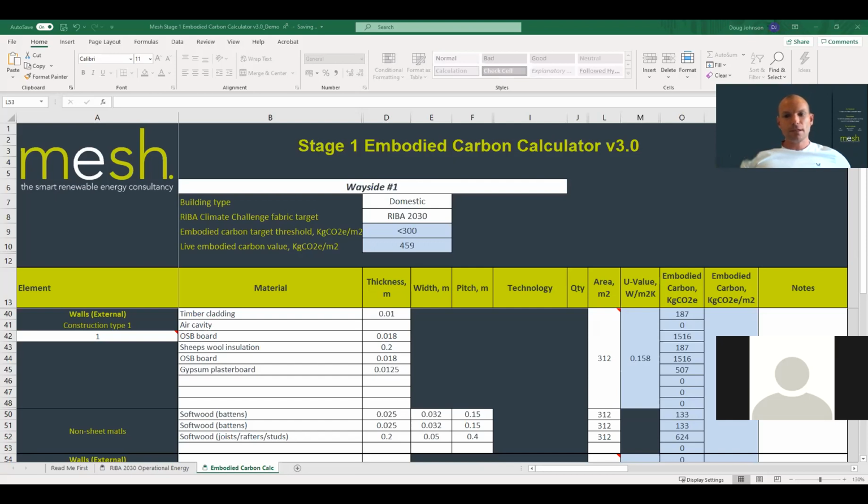But the U value won't be correct, so that doesn't comply with how you calculate U value. It's a fractionally different U value. I mean, none of this is to replace using like a BRE calculator or a definitive U value, but it's going to get you pretty close. To be honest, a timber stud in a wall of that construction will have negligible impact on the U value. It might have a tiny effect, but yes, it does affect it. Okay, so that's the definition of that.